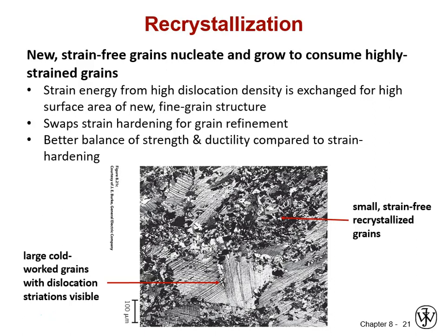So we gave it some heat, and you can see the upper red arrow on the right-hand side pointing to a bunch of much, much smaller grains, probably 2 orders of magnitude scale smaller from the looks of it. Those have no striations. They have probably 6 orders of magnitude lower dislocation density. They are effectively strain-free, but they're very, very small, and these are the recrystallized grains.